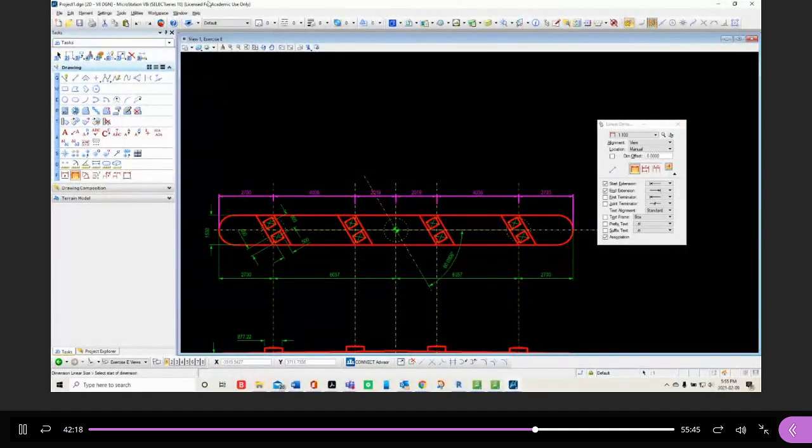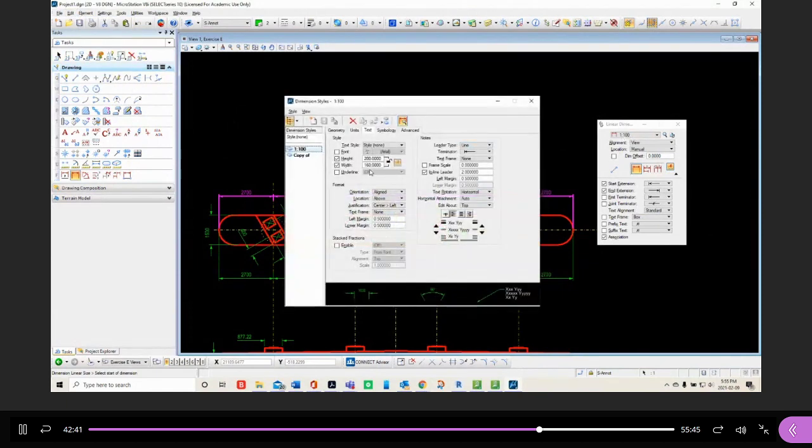Now, of course, you guys have to have created or have the annotations. So this is part of the annotations. If I start, here we go. This is the right size. So right size is 200 and 160. For text, guys, dimension style, 200 and 160 for your text. Otherwise, it's just too big. I don't know what I had 500 for.